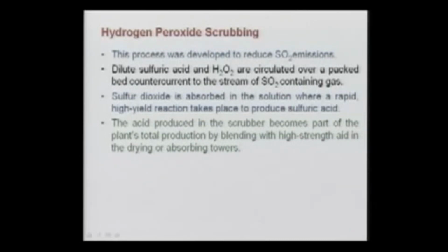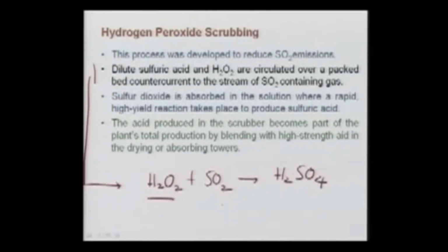Dilute sulfuric acid and H2O2 are circulated over the packed bed in the countercurrent direction to the stream of SO2 containing gas. This is really what is happening in here. Maybe I can write the equation here. It is H2O2 here, you see here, plus SO2. H2O2 is a strong oxidizing agent, and it will make the H2SO4, and almost all of this SO2 will be taken care of.